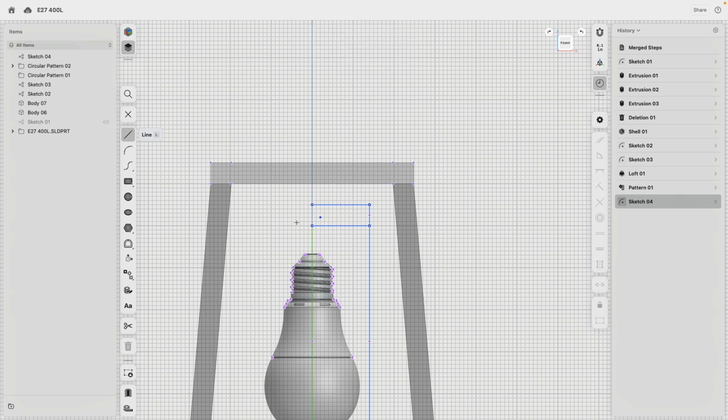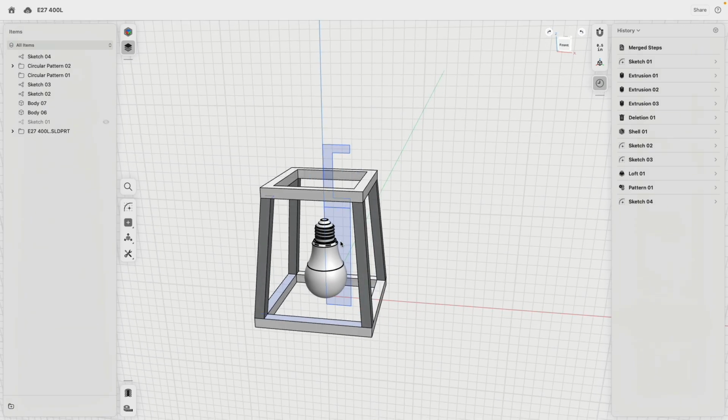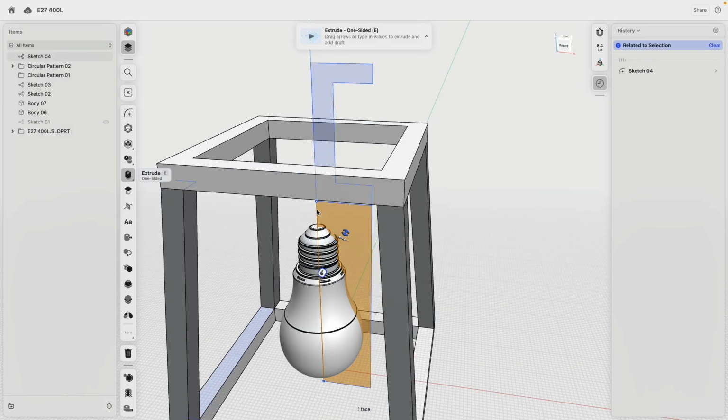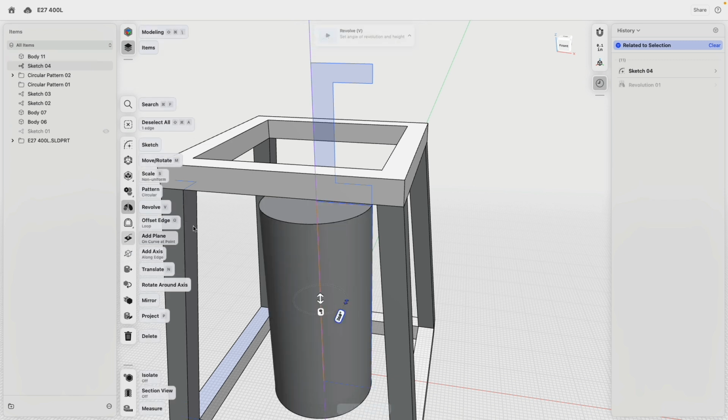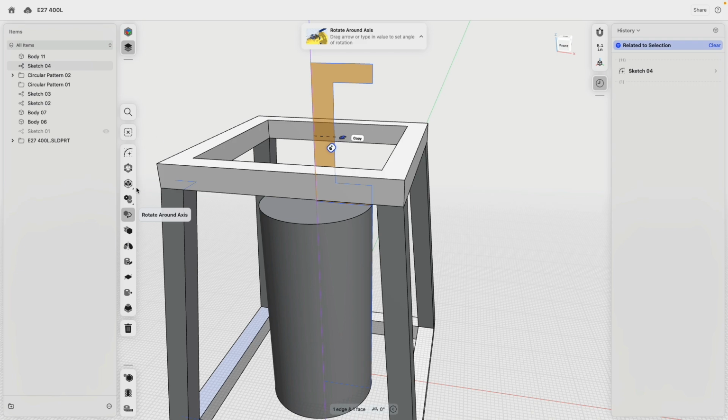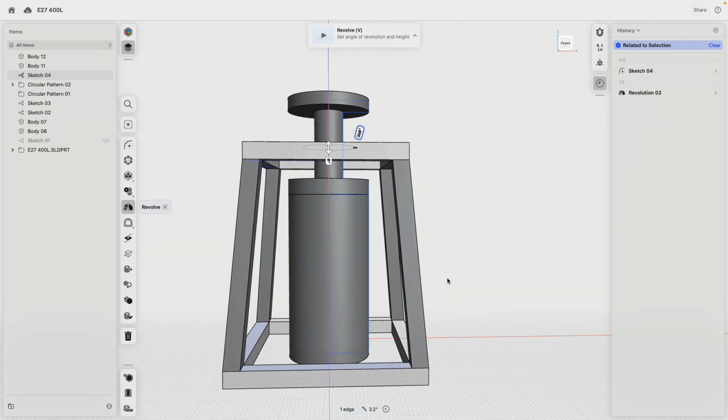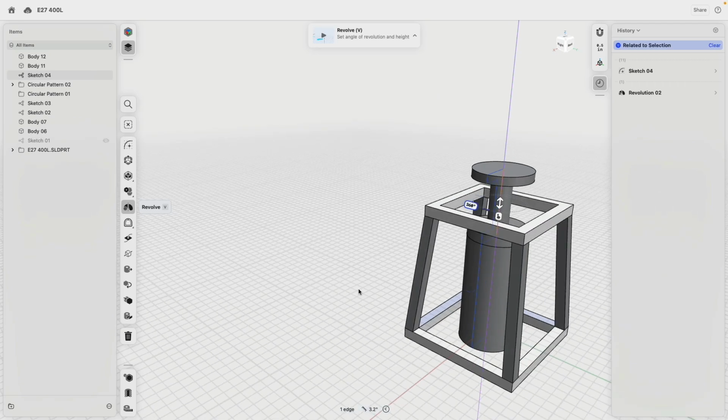Actually, hold on. Again, this is just only for the engineers a quick study. So horizontally over, then I go up, back, up, over to the z-axis, and then I go down. Yeah, okay. Because what I have now is, so this is going to be that illuminating material when the light bulb inside is on. Okay, so we select the sketch profile, select this sketch edge, then call this a revolve, and then here and there the same revolve. Okay, now there we can see everything.